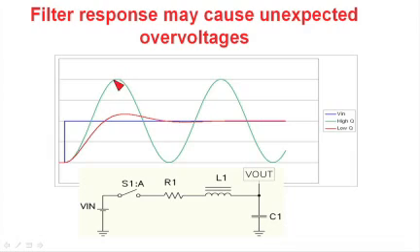We have seen this kind of problem in power over Ethernet systems where people have used relatively low voltage parts. They'll have a 60 volt part, 55 volt source, they apply the cable, and they damage their circuitry. To control this overshoot, one can just reduce the Q of the system. One easy way to reduce this Q is just to put the series resistance in and increase it. And you can see that we can control the amount of overshoot by adding this series resistance.